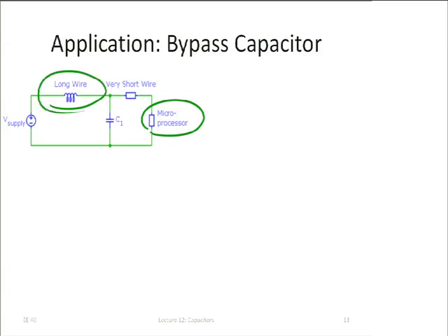What happens through a long wire, and we have swept that under the rug so far, is that it's difficult to get a lot of energy or a lot of current through very quickly. If you can run 20 amps in a long wire and keep it at 20 amps for a long time, that's no problem. But you can't, in a long wire, run 0, 0, 0, and then 100 amps, and then 0, 0. It just doesn't want to go up to a high current very quickly.